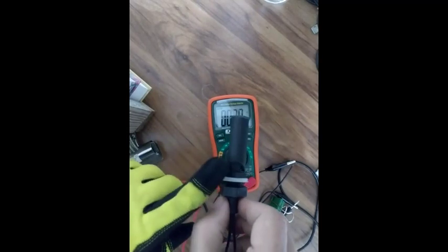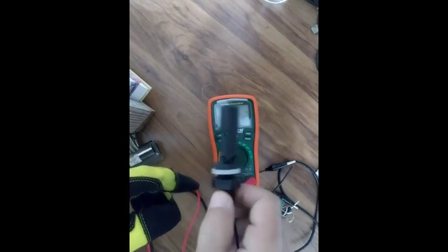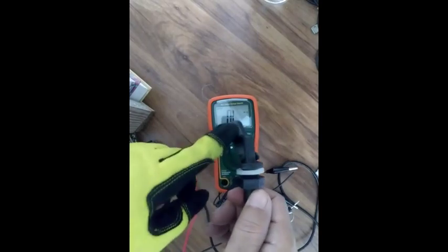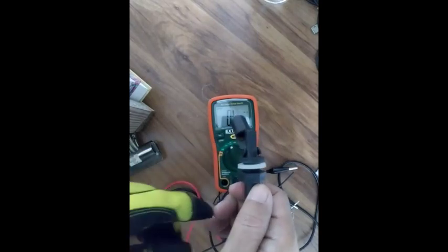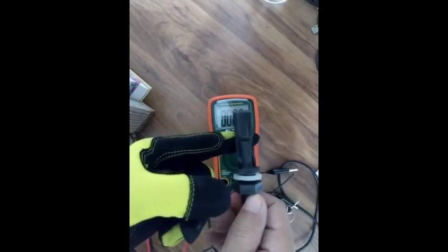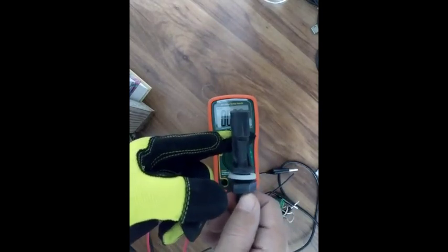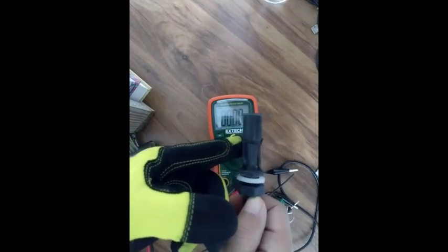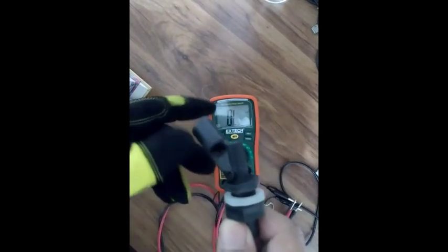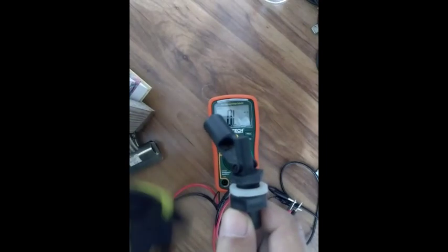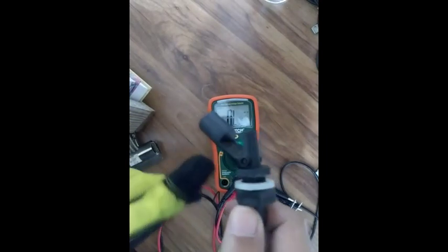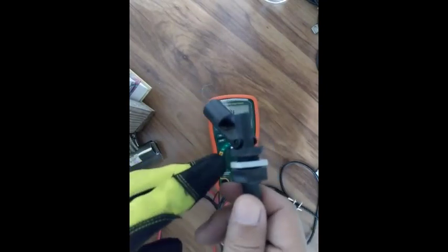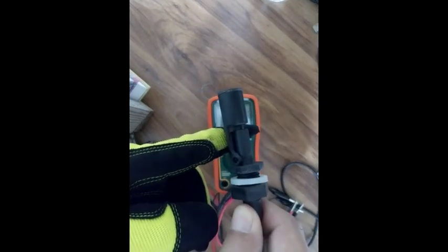Remember, I'm not talking about voltage, because some people get confused and quickly jump to say that if you have a circuit like that, that would be 0 volts, and when it closes, then you have 5 volts or whatever voltage you are using in your system. The answer is no. That will depend on whether you have a pull-up or a pull-down resistor in order to talk about voltage. The only thing you can talk about right now with a switch like this is either the open state or the closed state. That's it.